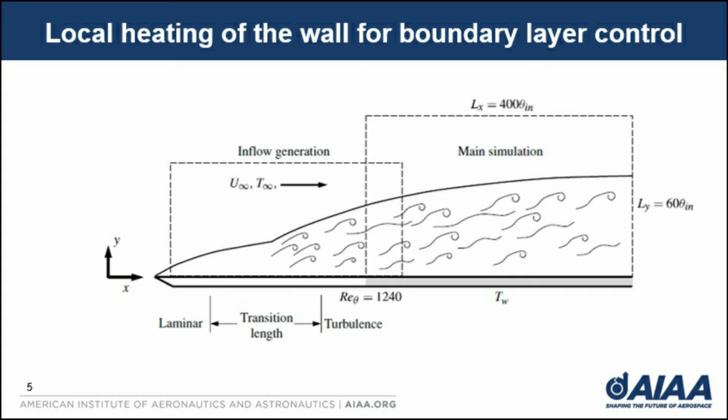is heated. The purpose of the current study is to investigate the influence of viscosity stratification by wall heating on skin friction reduction in turbulent boundary layers. The results provide clear evidence that wall heating yields skin friction reduction. Also, the turbulence intensity and the Reynolds shear stress were decreased in the heated flows. In addition, both the mean scalar and the scalar fluctuation of the present flows were reduced relative to the constant viscosity configuration. In regards to the power required to heat the wall, it can be said that this method is practical and could be used.